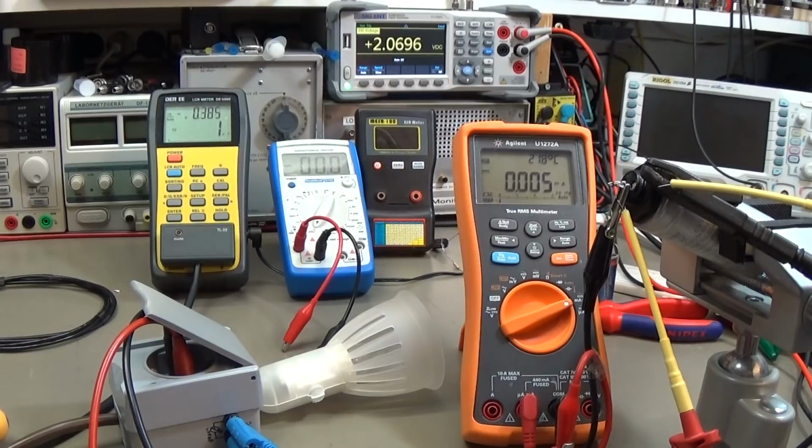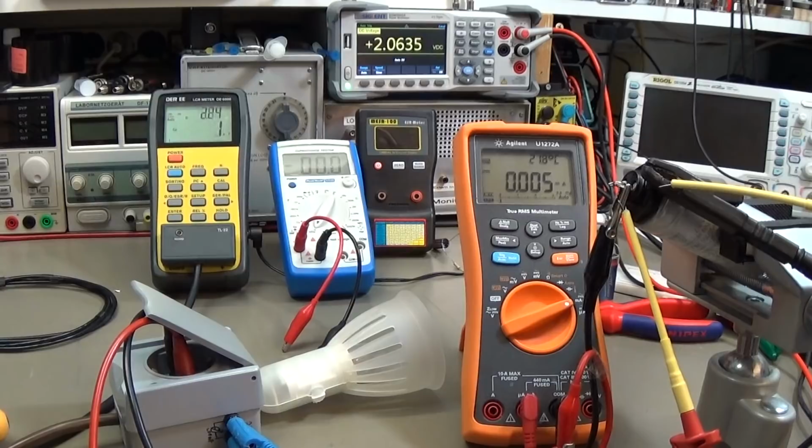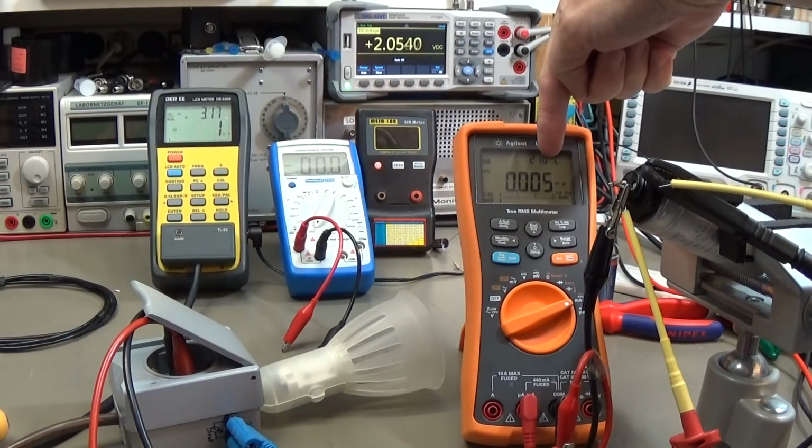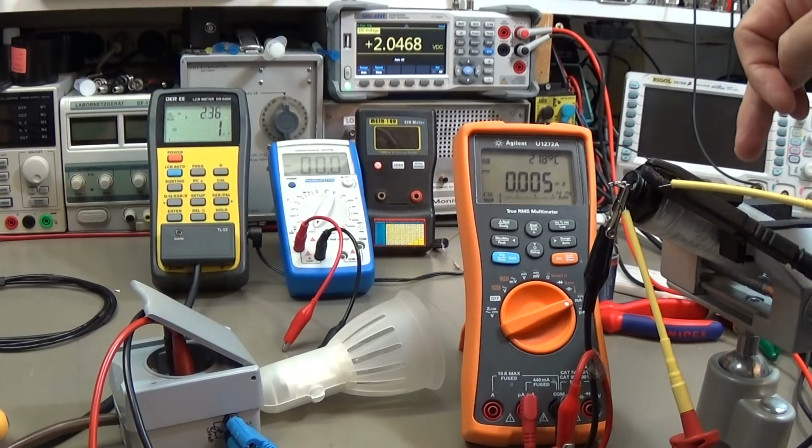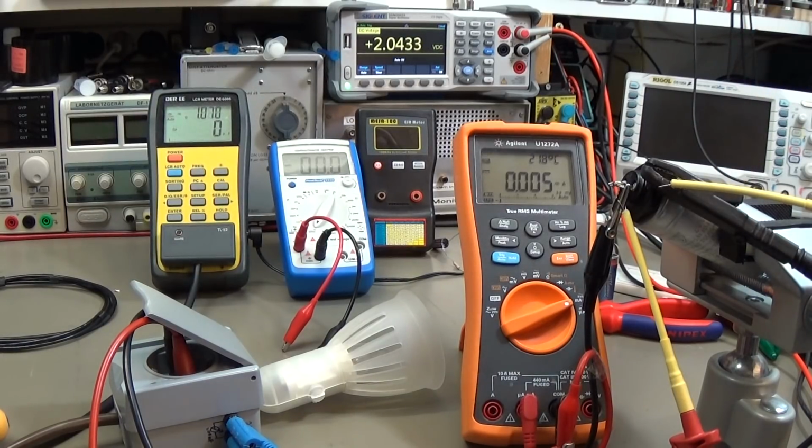And when I now crank up my isolation transformer, then you can read the voltage and the current, and what we want to see is finally an electrolytic capacitor which is not leaking too much current, right? And therefore let me start increasing my isolation transformer,